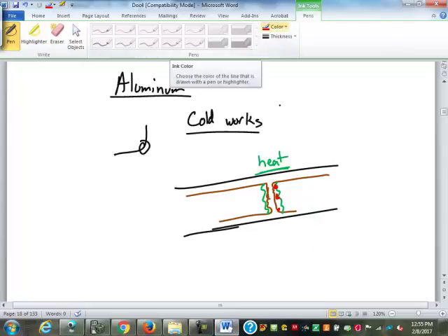So what you end up having to do is go upstairs and take off covers for outlets and pull them out and look at the wires. I've run into one that I can remember where they actually spliced wires onto the outlets and pushed the aluminum out through a hole in the back of the box. So there's copper in the boxes. They probably didn't know what they were doing at that point.